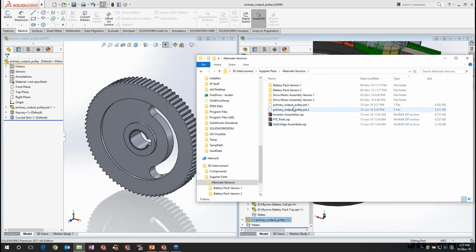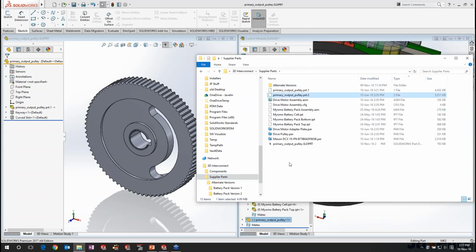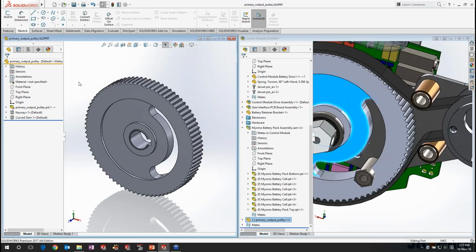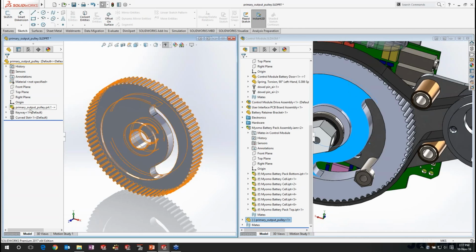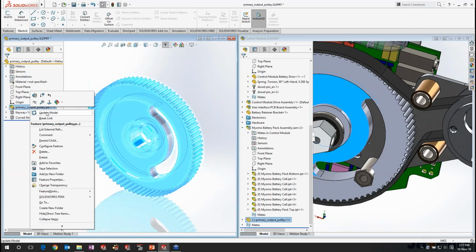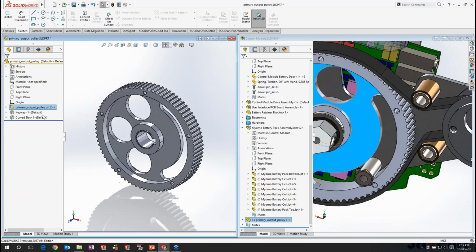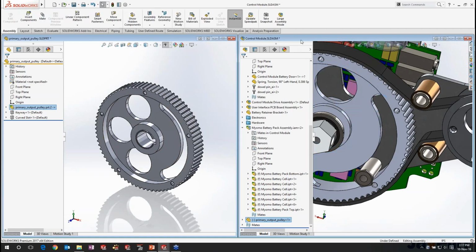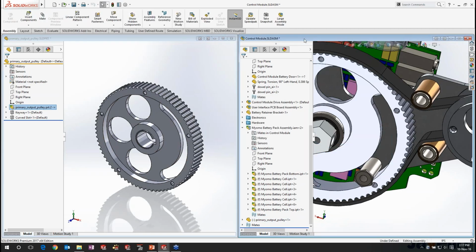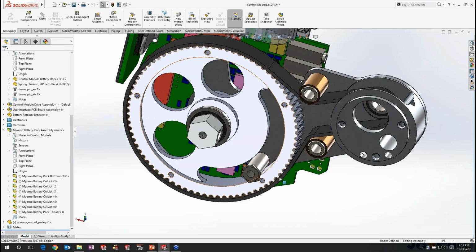So we're going to take this .2, and if again we put it into our project folder, back inside SOLIDWORKS, it's going to see the update option. So again, we can just right-click and choose to enable the update, bring in the latest geometry. But again, none of the features that we've added, the relationships and so on, have been lost. They're still all intact. And we're seeing that come across here to our assembly file. And that's going to fit for us now.